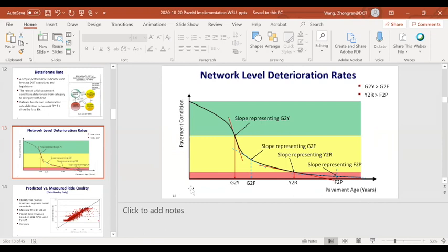Definitely, they will consider all this loading, the truck loading, lane motion, data, stuff like that. And definitely they will consider our model, or the distress model, is individualized. So our model, if we talk about cracking, we model the longitudinal cracking, alligator cracking, and lateral cracking also. For PCC, we also model different types of cracking individually. And later on, we add them up.